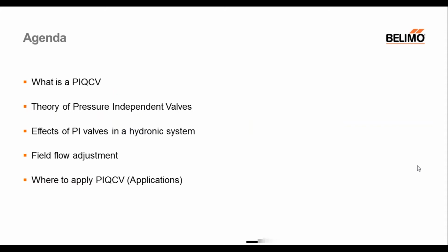I'll talk a little bit about the theory of pressure independent valves. I'll also talk about the effects of pressure independent valves in a hydronic system, and tell you how you can adjust flows in the PIQCV in the field, and lastly, where we see the PIQCV fitting in the HVAC applications.